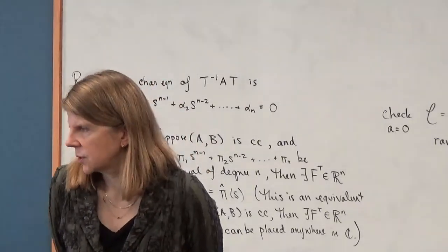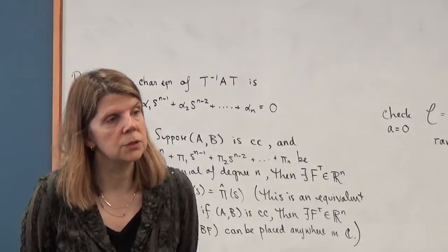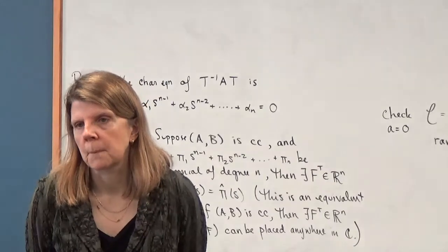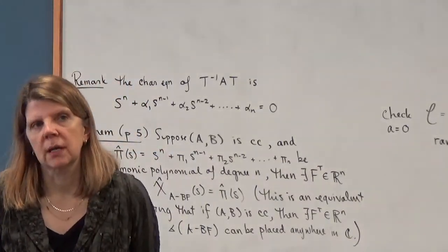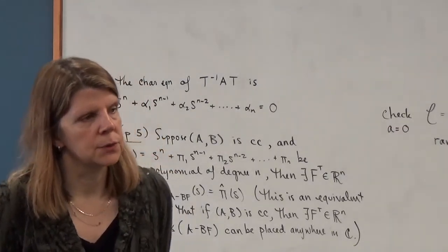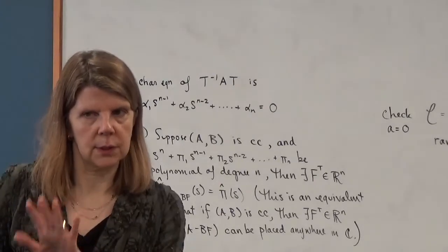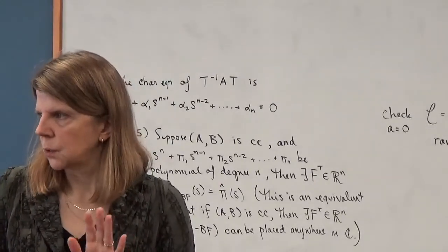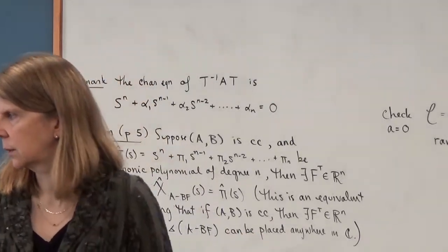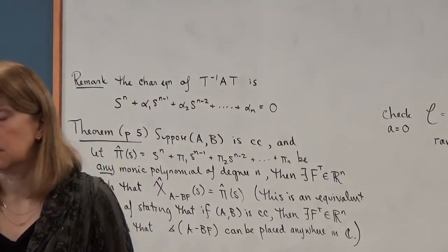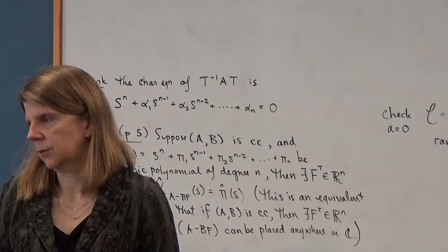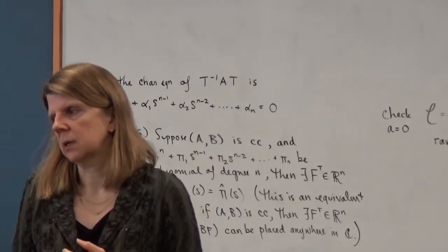I mean, this is a very generic question because it really depends on the system at hand, but how would you choose F? What are some considerations you would put in for choosing F? Let's talk about what you would try to do to those eigenvalues from the open loop case, where you've got some unstable and some already stable, to the closed loop case. What would you want to be able to do with F? Just stabilize it. Okay, so you'd want to move the eigenvalues that are unstable over to the left half plane. Yeah. All right, so you want it to be stabilizable.